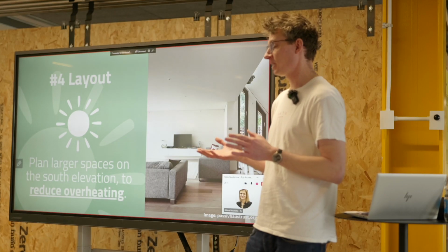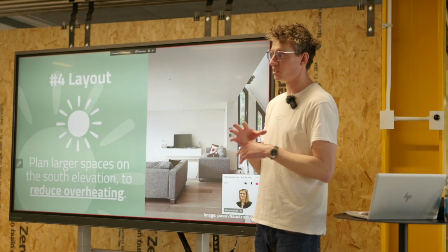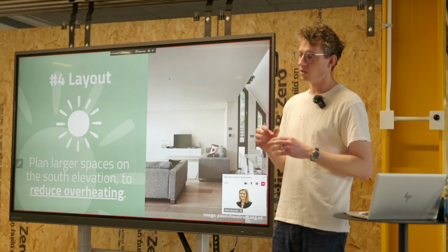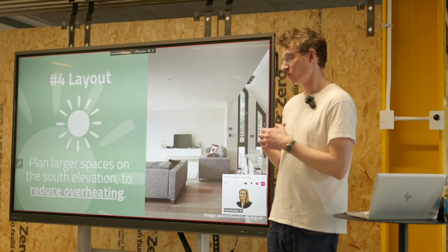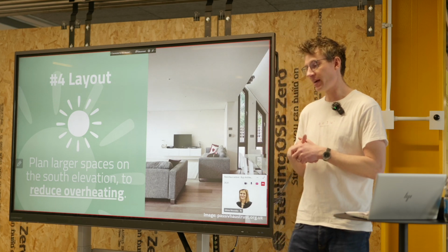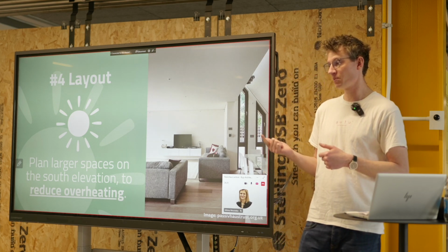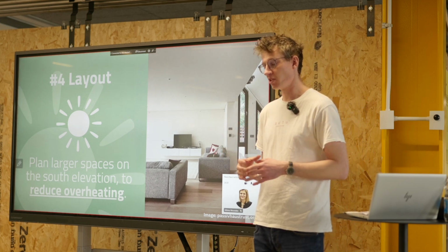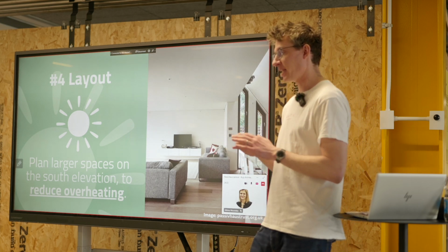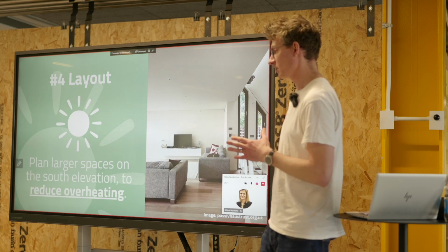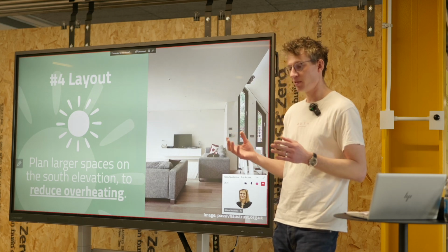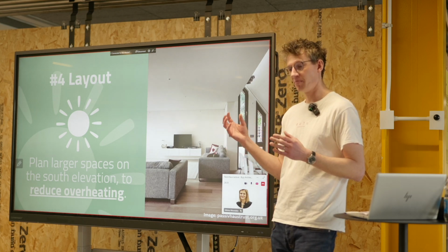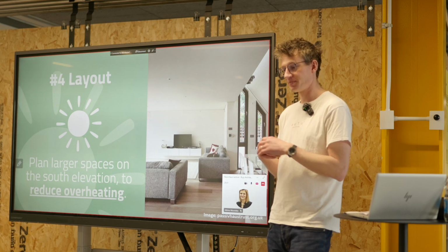Each room in the building then will either have a supply duct with fresh air, or it will have an extract duct. And the rules are that you provide fresh air to your living rooms and your bedrooms, and you extract air from your kitchens, your bathrooms, your utility rooms. And there's a balance as well that happens in the property, where the same quantum of air needs to come into the building as is being extracted.